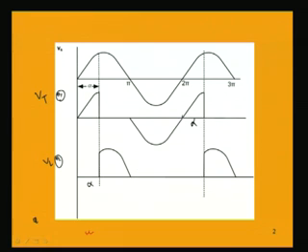and again from this point till alpha angle is crossed, the voltage will continue to be 0, since there is no current flow in the resistance, the thyristor is not firing. So the voltage is 0, and once the thyristor fires again in the positive half cycle, after this angle alpha is crossed, then the voltage across the resistance will again be equal to the input voltage. So, these are the waveforms of the voltage across the thyristor and the voltage across the load.